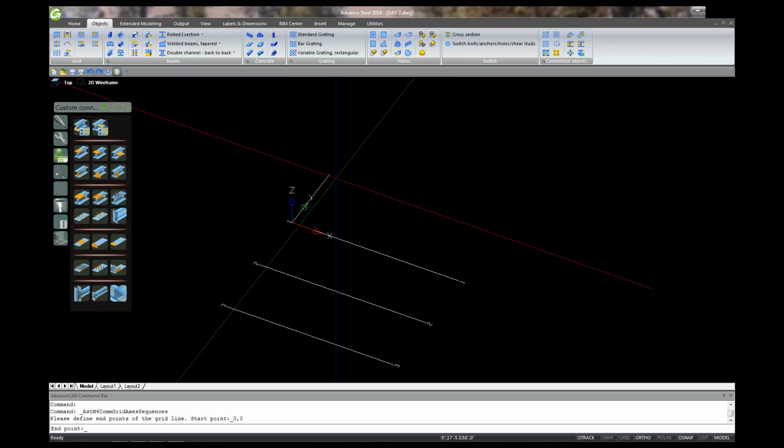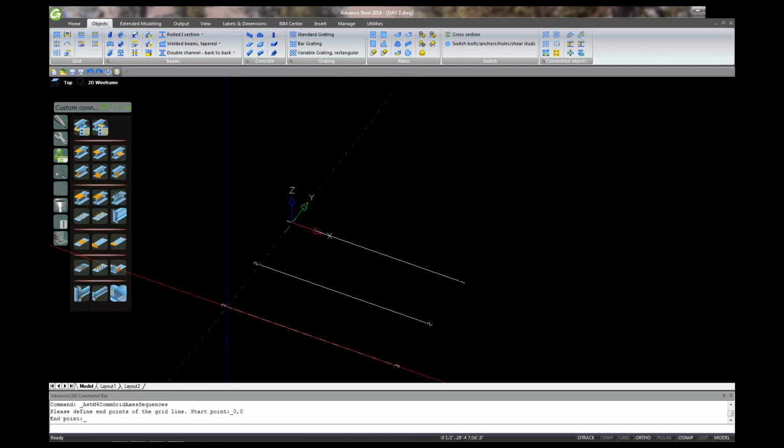They have to be to the other side, but it doesn't matter. You cannot change the position, so for Y direction, you need to click on first point where you have your UCS, and the second point would be number 3, where you have the number 3 axis. I don't need to enter a distance here? No, you don't. It's going to be your end point.